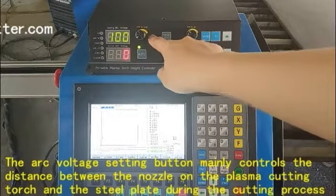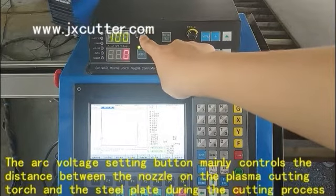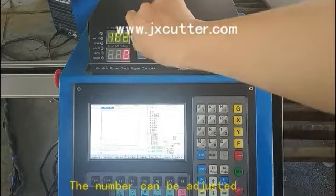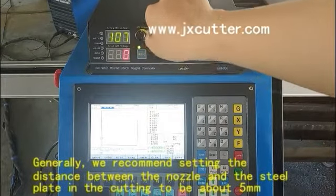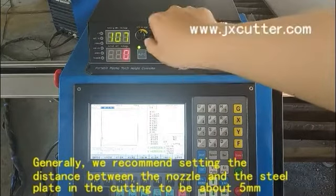Setting button mainly controls the distance between the nozzle on the plasma cutting torch and the steel plate during the cutting process. The number can be adjusted. Generally, we recommend setting the distance between the nozzle and the steel plate in the cutting to be about 5 mm.